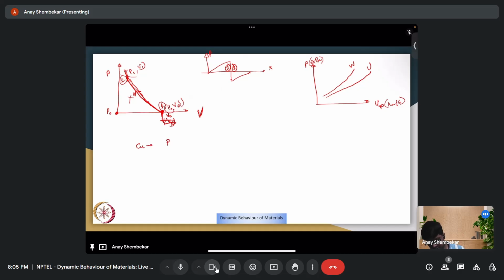So suppose you have copper. If I write pressure, density, specific volume ratio, shock wave speed, and the particle velocity. At zero pressure, you have density 8.93, this is gram per cc, pressure in GPa, and these velocities are both in kilometers per second. No change in specific volume, 3.940, very little particle velocity.